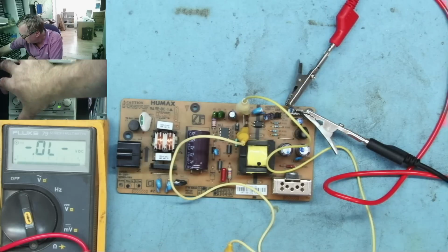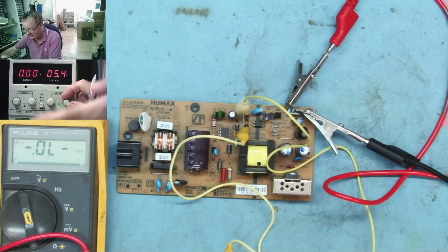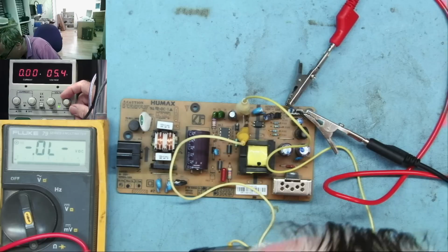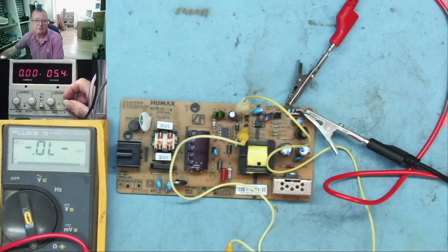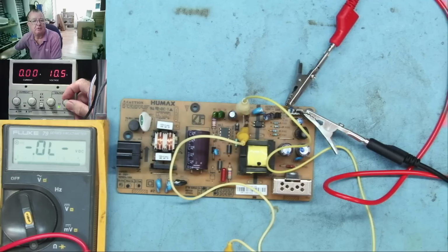Okay, right, we switch on. You can see the bench power supply, no volts, no current. This is reading open. Right, let's start increasing the supply voltage. This is a 12 volt power supply. Yep, it's a 12 volt power supply. So when my bench supply gets up to 12 volts, we would expect the opto-isolator to switch, and this should read it. Let's have a look.